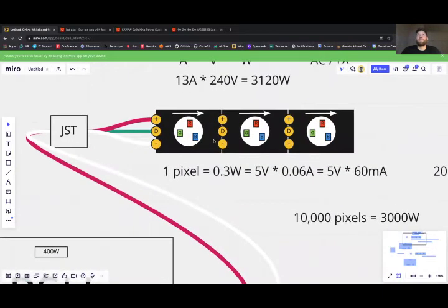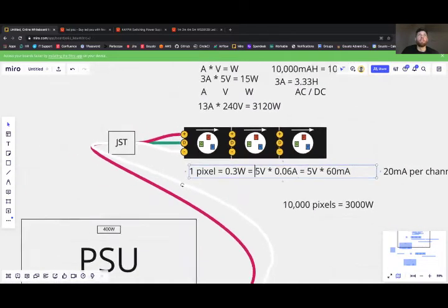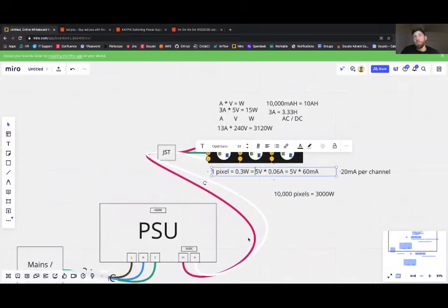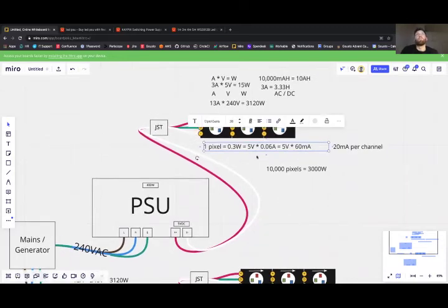And in reality, since they're well-engineered, sophisticated electronic systems, they can tolerate a little bit of variance around that 5 volts. So in practical reality, it doesn't have to be bang on 5 volts. I think they can operate down to something like 4.5 or maybe even 3.3. Don't quote me on that. But ultimately, it is possible that you make your cable so long that it incurs a quantity of voltage drop, which is unsustainable for your LEDs.